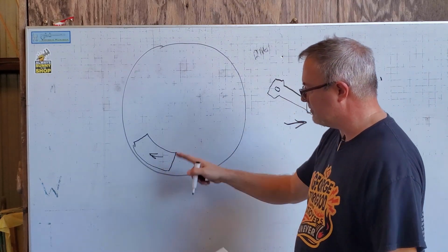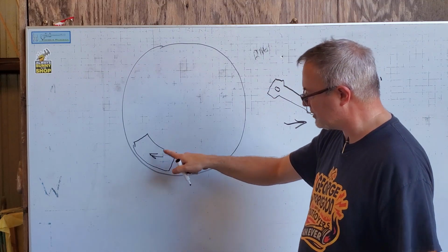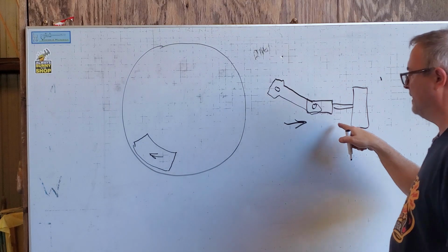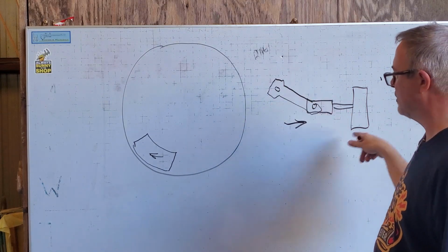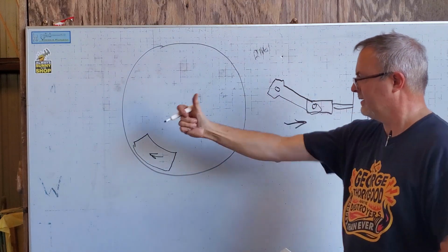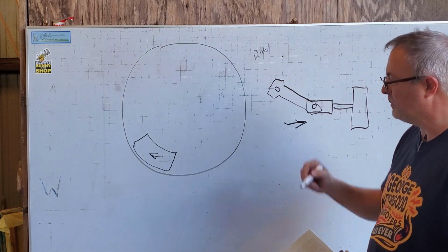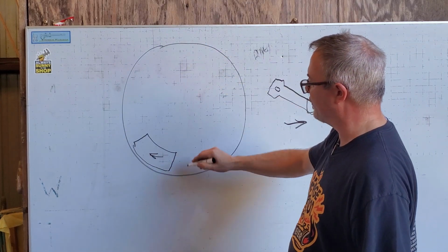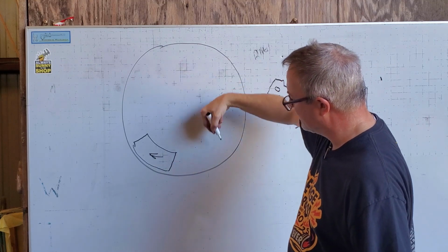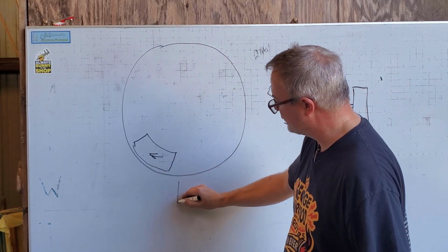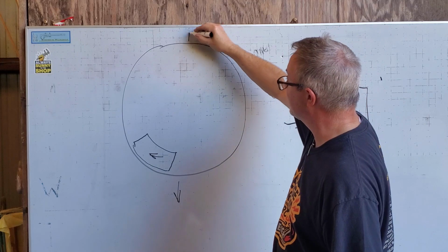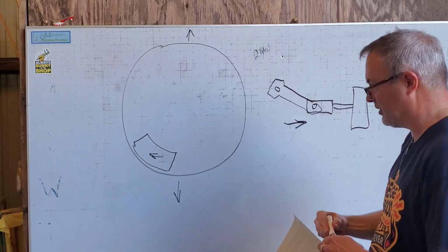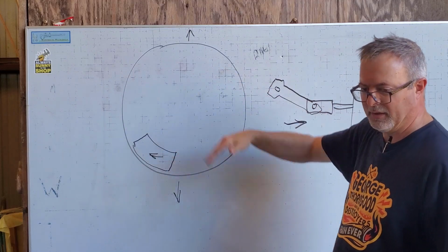You can do the math, and you can just about completely balance out the horizontal forces of that counterweight and horizontal forces of all of your components moving this way. But what this does then is, in the up and down direction, it's going to be putting force both into the foundation and up here. It's going to tend to be lifting the engine off of its foundation. So it's going to put a hop on the engine.